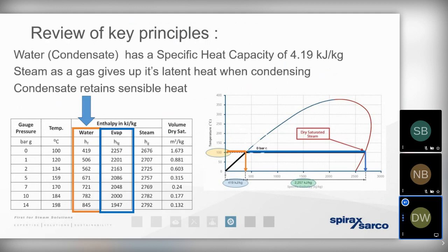And that's critically important whenever we're talking about steam quality, steam condition. Why? Well, the wetter the steam, the more likely that steam is to condense out in the distribution pipework. So of course, that's going to represent an energy loss. We're likely to see energy starvation or steam starvation at the process. But if we get more condensate that exists in the distribution pipework, we're more at risk of erosion, corrosion, and water hammer.